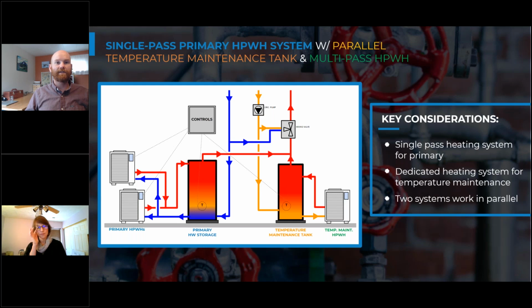But when there's little use, it has not as great of control over those lower flow rates. And so it's good practice to specify parallel valves for our larger buildings, because then we can get good control over both the high and the low flow rates that we see during normal operation.